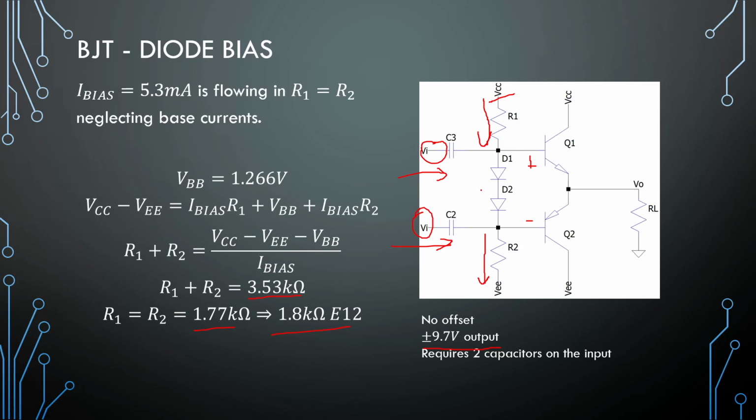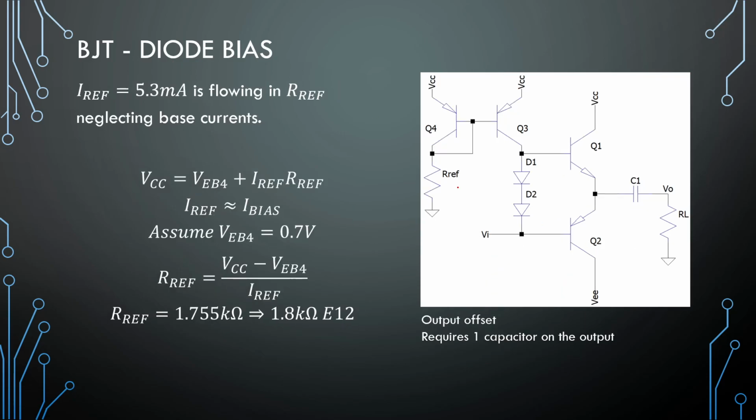Right, and that is doing the bias with resistors. Then the current source. So the assumption is this point is a ground. Now this circuit here in the corner is the most basic current source that you get. Note, this transistor Q4 is diode connected.